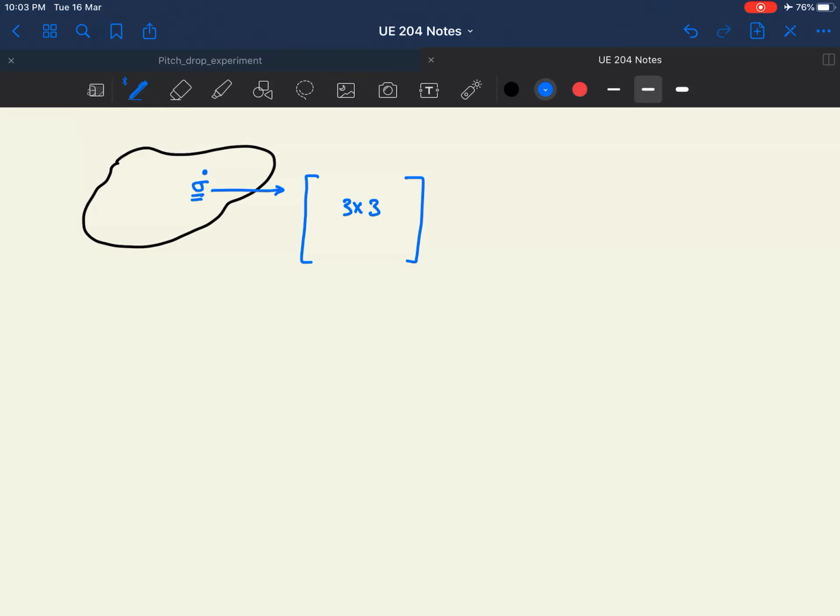Now this stress tensor, you usually have to find values for these numbers. These numerical values cannot be found until you tell people what the axis is. Without giving this axis, the numerical value cannot be found. As you rotate this axis, this numerical value will keep on changing, but that does not mean that the stress situation is changing, right.